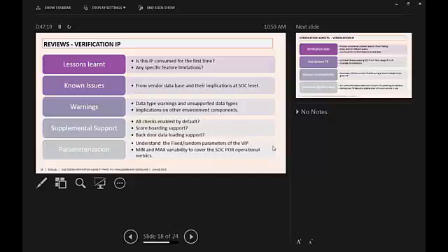And these are warnings. Sometimes when we try to run the simulations, we saw some warnings like UVM error to warning. For some other purpose they have added this UVM error to warning, but that is required for us, because that is something related to a scoreboard. So we cannot have a warning in the scoreboard if there is a data mismatch.